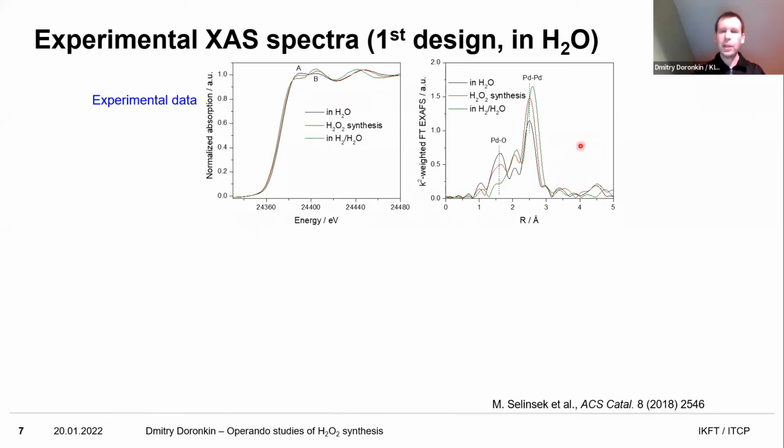And the spectra were measured, as I told before, we had 6 conditions at least, and for each condition, we measured at different points in the catalyst bed, at the inlet, at the outlet. When you are studying catalysts, it's also important to remember that in plug flow reactors, you have a conversion, which means for fast reactions, you may have at the inlet of a catalyst bed, the catalyst which sees only reactants.